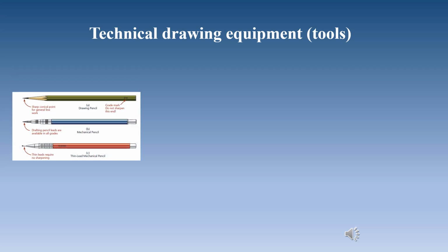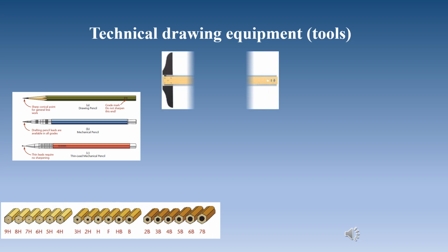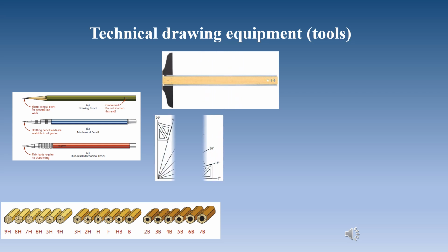The drafter uses several technical drawing tools such as pencils, pens, set square or triangle, compasses to draw curves and circles. Drawing pencils should have a high quality to help produce good quality technical sketches and drawings. Use light lines for construction lines, lettering guidelines, and precise layout work. Use dark, dense black lines for the final lines, lettering, and arrowheads.